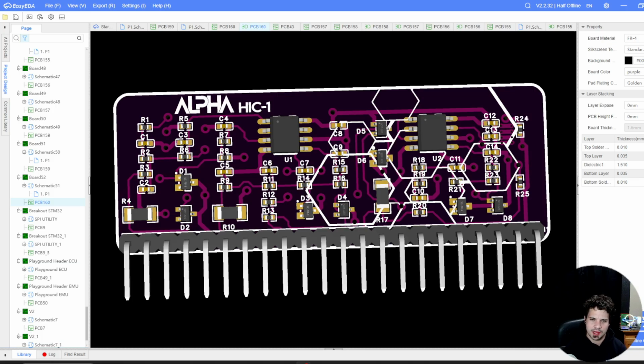And something I've seen with other people doing this is they're using op amps in place of the original comparators, even though it's a comparator circuit. And the funny thing is when you put an op amp in place of a comparator, if the circuit is designed as a comparator, the op amp will mostly work as a comparator, but there are certain thresholds that it can't keep up with. And I've also noticed that some of these other people are using gigantic capacitors on here, which don't align with the way that the network is actually set up to clean up.